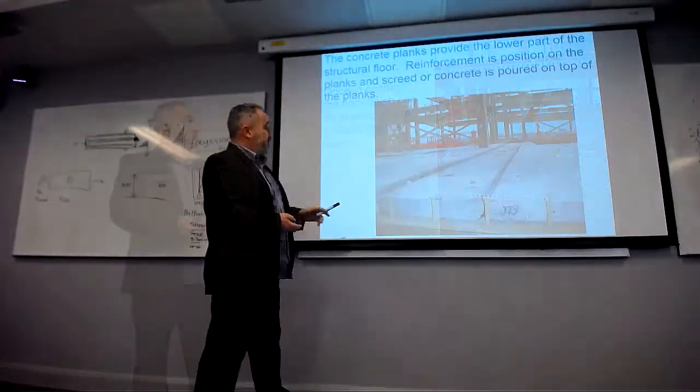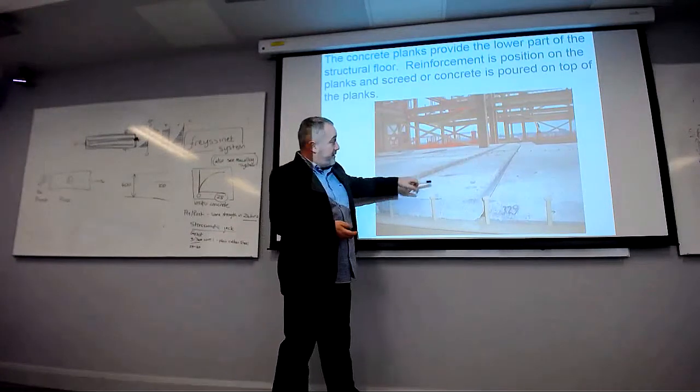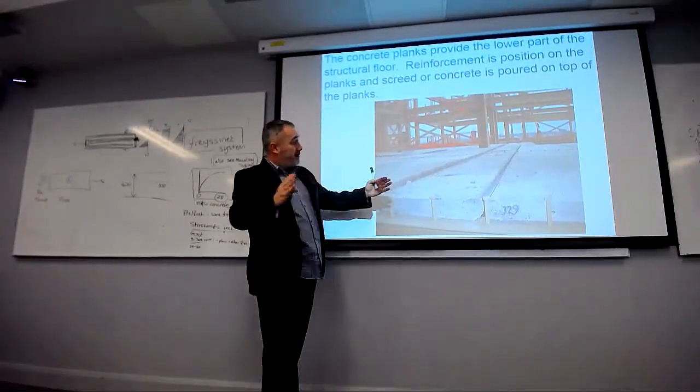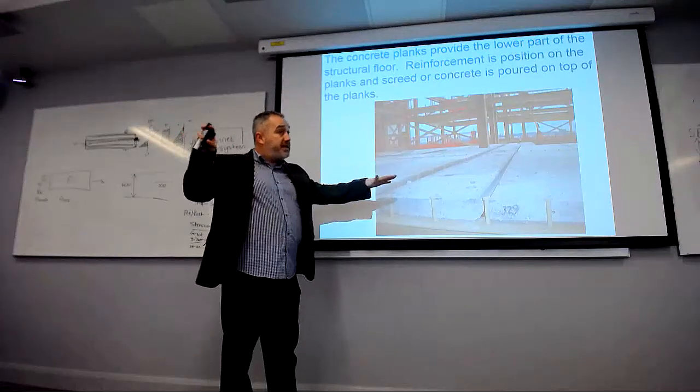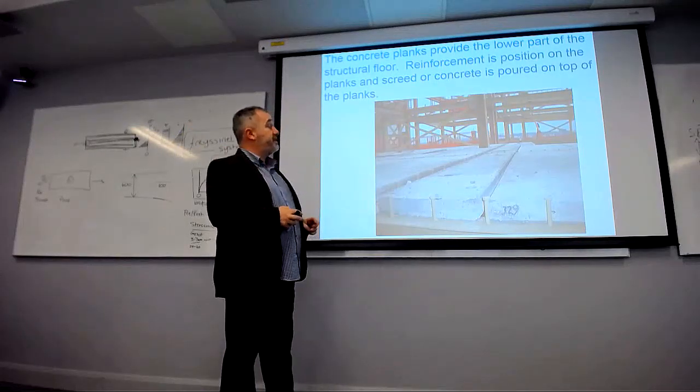computers. There's an example of solid planks, not as wide, but they're really long. And you've got your steel beams, you've got your shear studs. What the shear studs do, when you put your grout screed on top, is connect the floor to the steel beams, and it becomes like a diaphragm, which makes the building all rigid.